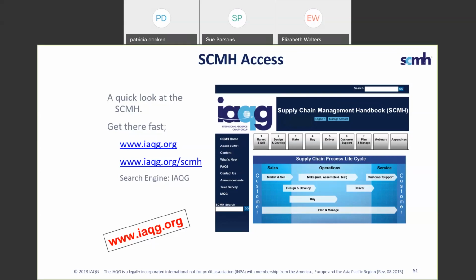Whether you have a new product or an existing product. If you have an existing product and you're shipping non-conforming product to your OEM, he may request that you do a PPAP and that you put a process flow, a PFMEA and a control plan into place to control your variation, to control key characteristics so that you can not send non-conforming product.